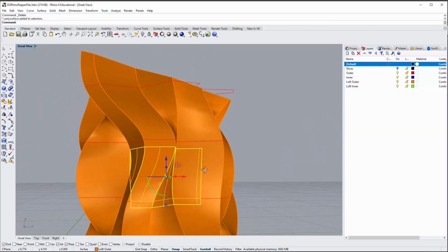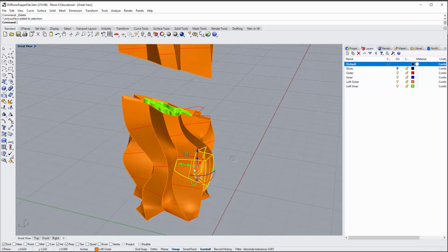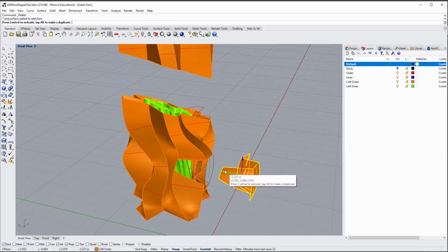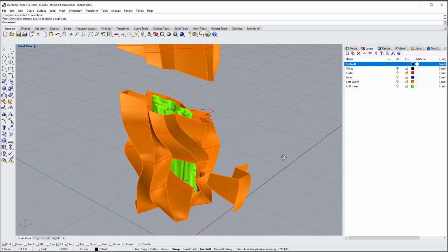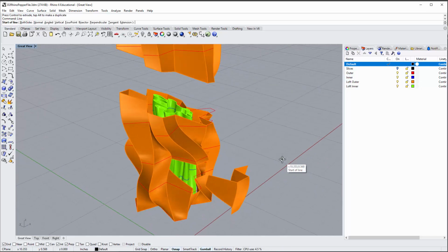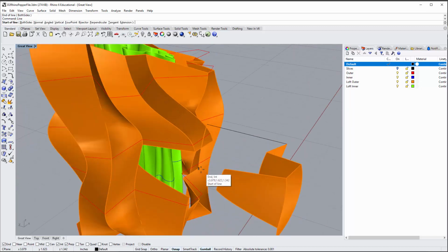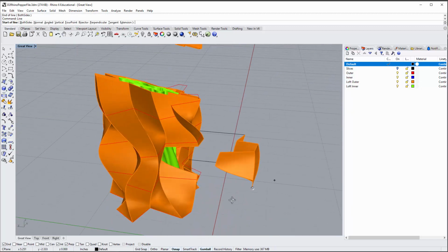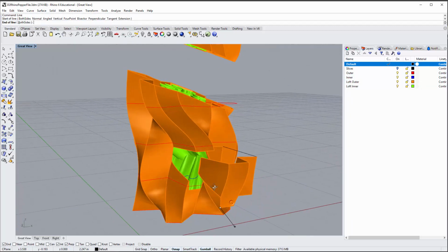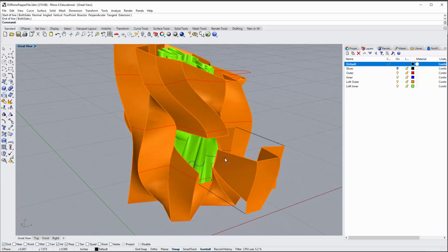If I look at it straight on, this is basically the box outline, where it was intersecting. So we can pull it out a certain amount, maintaining that axial relationship with it. And then just draw lines, so line, snapping to the corners. Same thing here, same thing down here. I'm just using the right mouse button to repeat the last command very quickly.